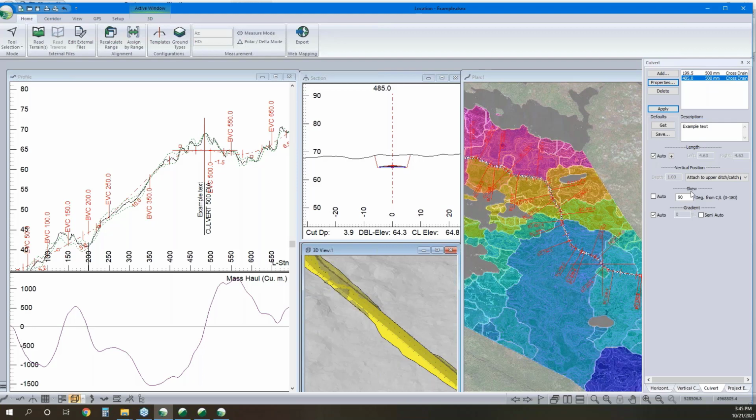The next question, I'm going to say second last question here, just based on time. How is culvert embedment handled? Yeah, so with the minor culvert, you're not going to actually take into account the excavation of your material under the pipe, but you could control that by using your minimum fill depth or fill depth at center line to adjust accordingly.